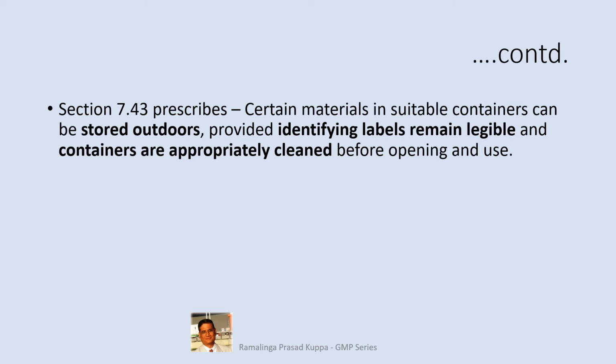Sometimes metal tags may be fastened for such outdoor stored drums. They will not peel off or fall off. Since the containers are stored outside, there is a possibility to collect a lot of fine dust over it. Your SOP on handling and dispensing should have a provision to clean the drums before being opened and dispensed.